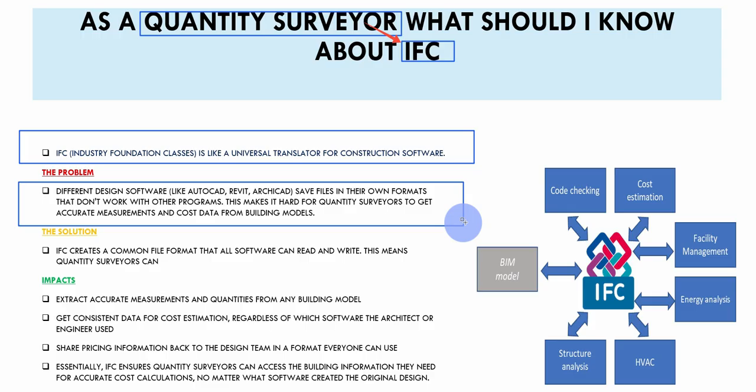For example, I can operate a Prota Structure project and get the reinforcement schedule and the concrete quantities. But as a quantity surveyor, you cannot really use this software to get quantities; you need IFC skills to be able to use it, which is what is coming next. So to make it easy for you, you need to use the IFC file, then you can get accurate measurements and cost data from the building models.